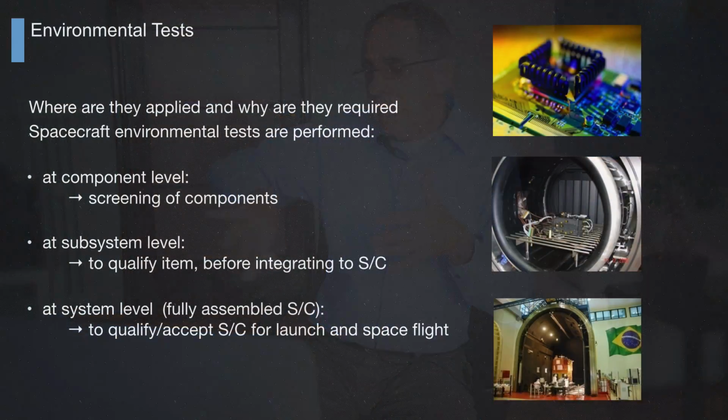So we try not to use them anymore because they can fail during the orbit. We skip them and do not use these components. We can retest them in our laboratory after shipping. We make sure we use all the good ones to build the spacecraft itself. The ones that are very close to failure, we force them to fail in the laboratory. So this is the component level.